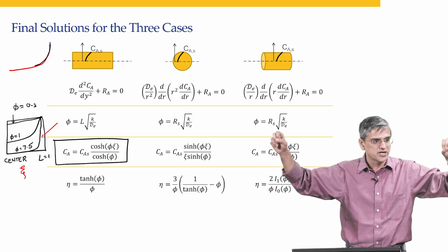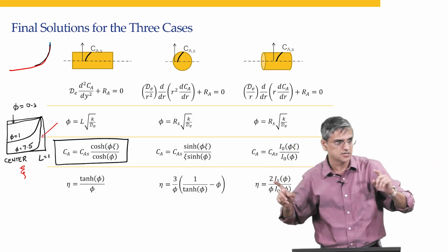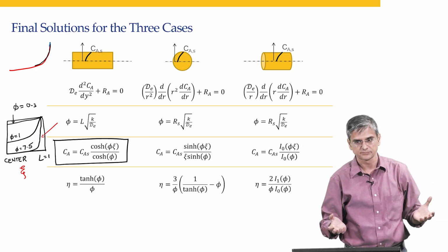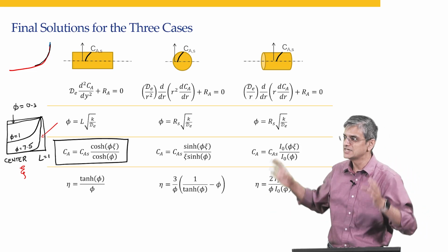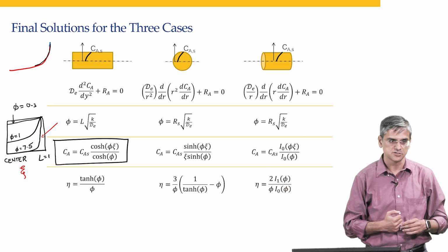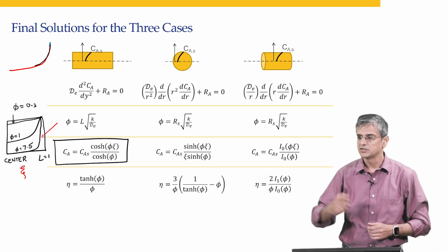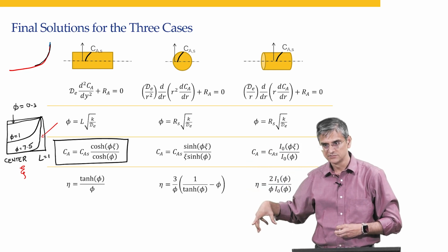Effectiveness factor is 0.1. It's almost as if, again don't take my statement literally, only 10% of the pellet is used. With the 1 mm pellet, it's almost as if 95% of the pellet is used. That's the physical significance of your eta.